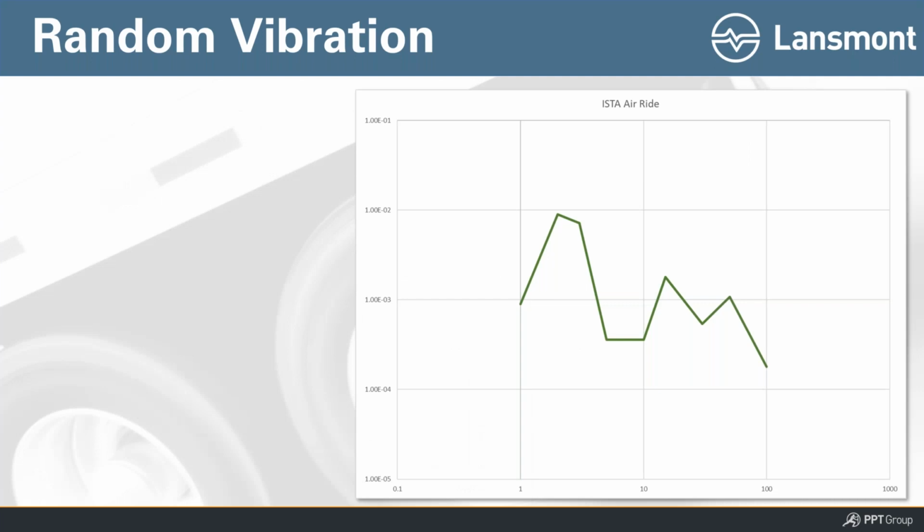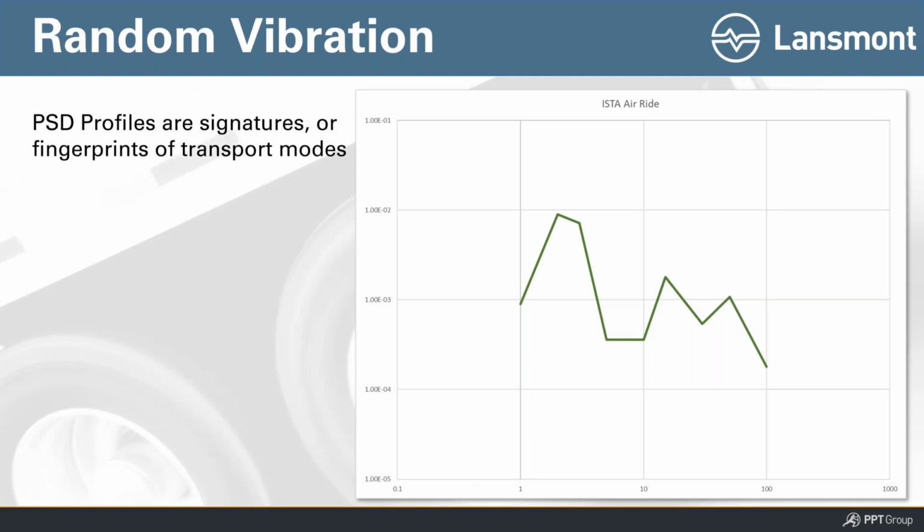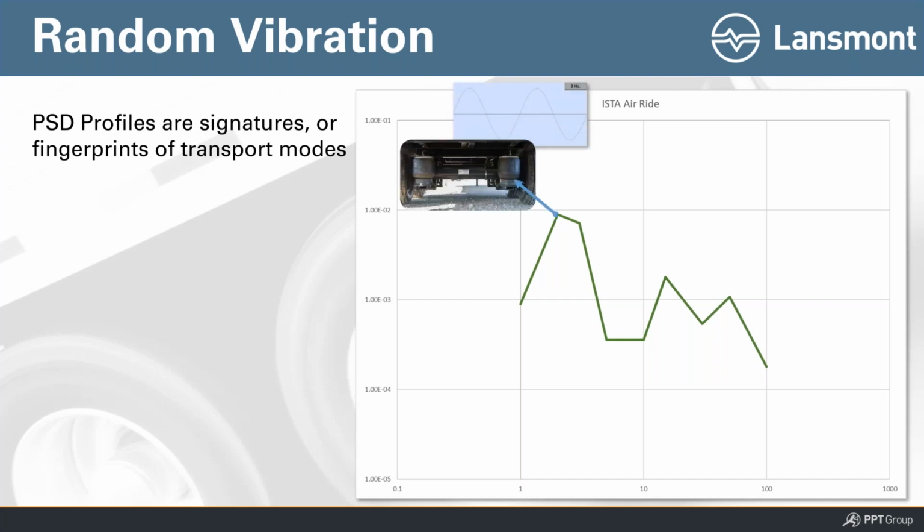So, PSD profiles. What are they? I've said in even the previous webinar that I hosted on random vibration testing applications, I think of PSD profiles as the signatures or fingerprints or identifiers of transport modes, right? So the shape of that curve on the right-hand side, that green curve, and the intensity of it speaks to what the mode is.